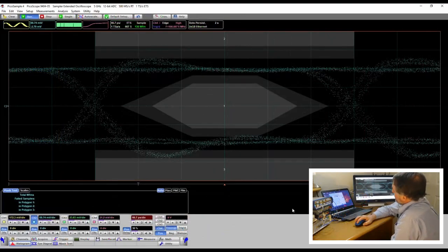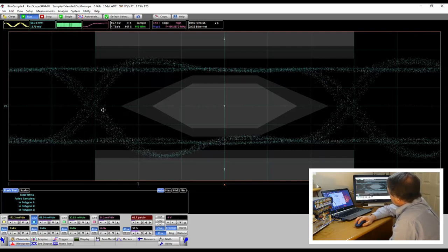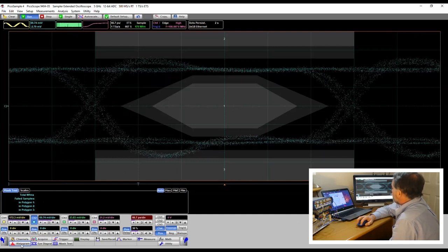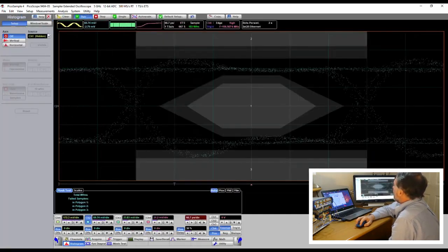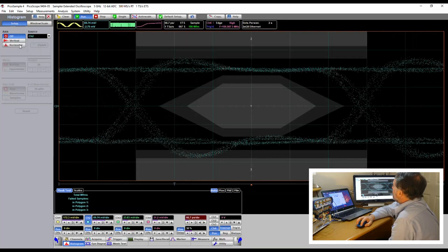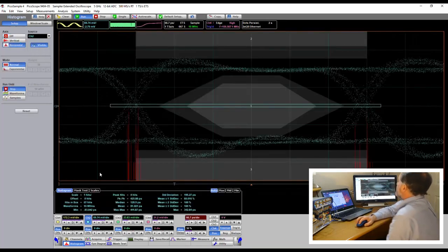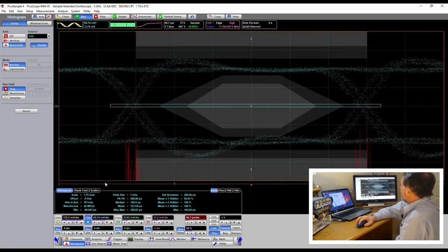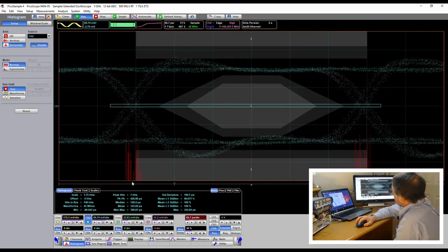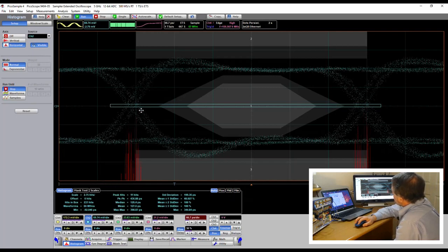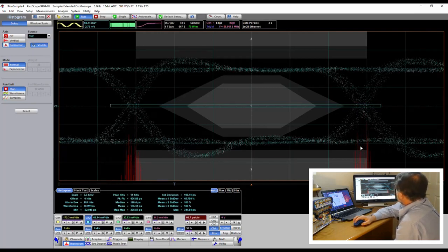So we can bring a little more clarity to the picture here if we choose to add a histogram to channel 2 horizontal, and here we can see that's just beginning to build there, and what we're going to see build is a bimodal histogram at the 2 locations.